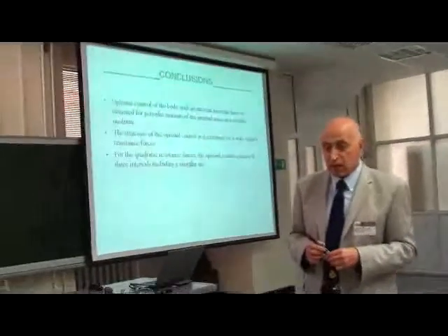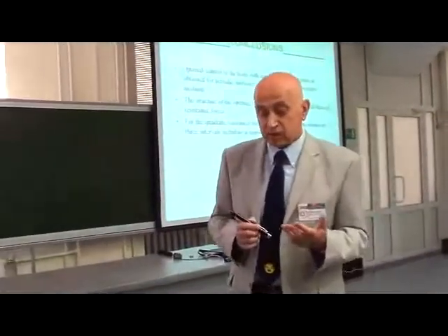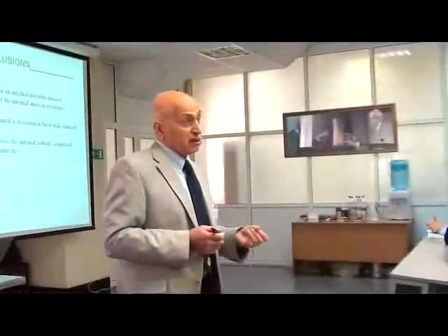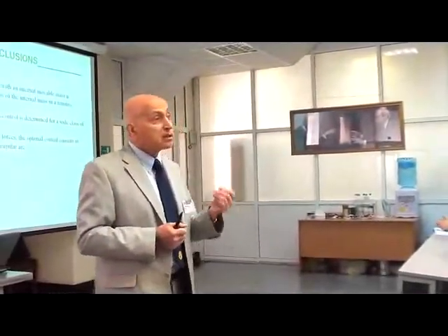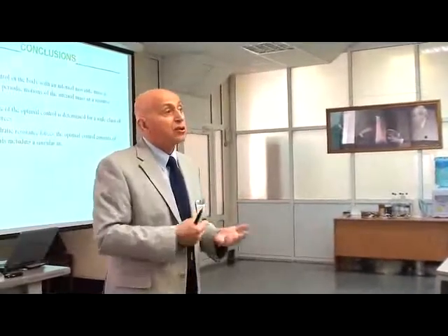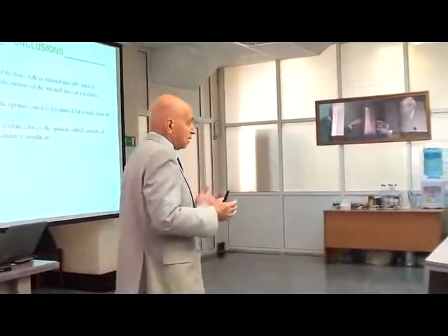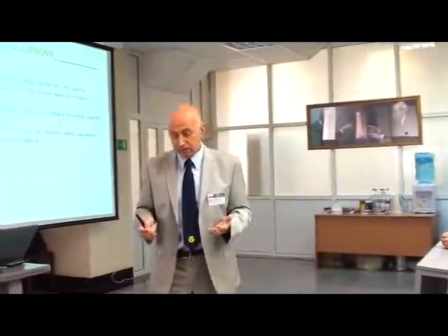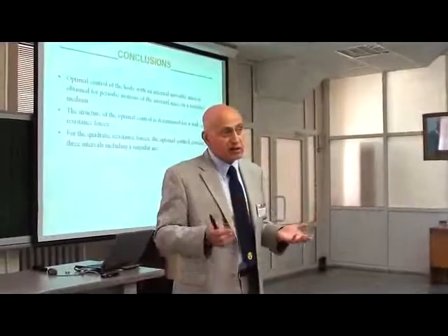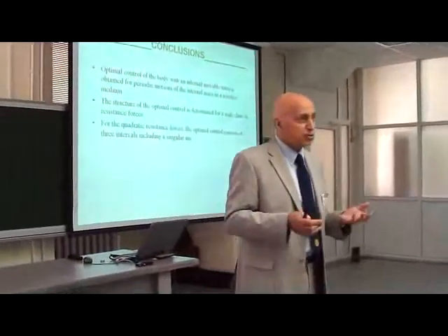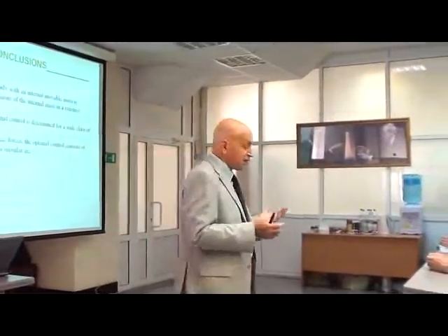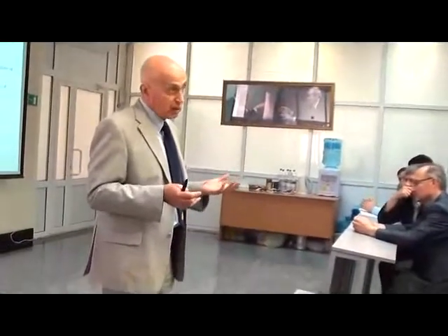And the second, of course, our resistance assumptions are very rude. We just assume that we have only a simple formula depending on velocity. If we consider a body moving in a fluid, we know that there are a lot of vortices and many other things, and hydrodynamics is, of course, much more complicated. But for some cases, maybe this can be considered as a starting point. I'm sure about it.